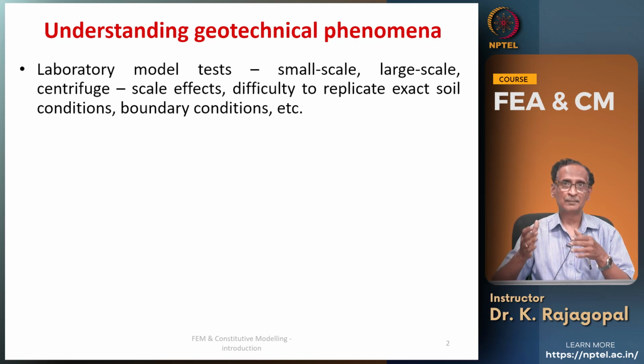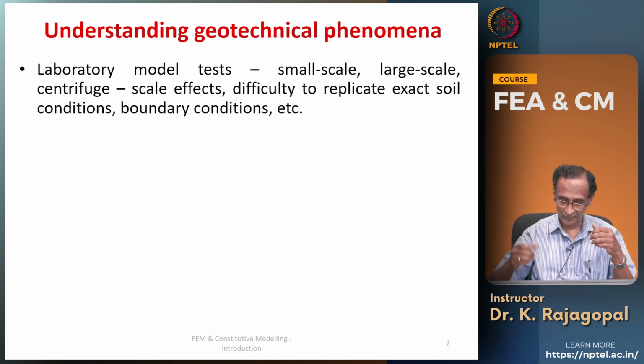Then other difficulty with these laboratory tests is the boundary effects. Because of the necessity, we take a small model, and that boundary may be too close to the applied loading, and because of that we may get a stiffer response than what it should be.